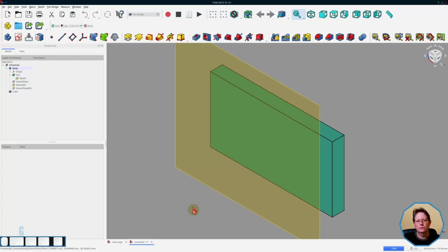Because once a plane is attached to an existing feature, you need to change the attachment point in the local coordinate space. But if you don't attach a plane to an existing feature, you have to do it in the global coordinate space. It can do your head in a little bit, as it did for me for a little while, but now that I understand it, it makes sense, and I find that it works really well, but your mileage may vary.